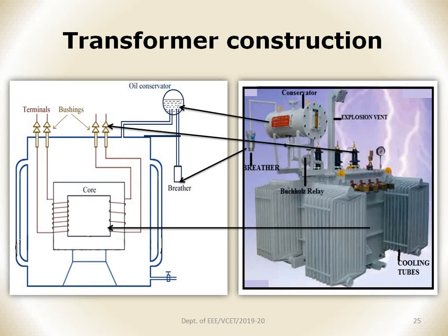You can find a current flow provided the secondary end is closed. Depending upon the requirement, you can either increase the voltage or reduce the voltage, and this increase or reduction can be decided by the number of turns provided on the primary end and the secondary end. The number of turns is one of the important parameters that decides the amount of transformation taking place inside the transformer.